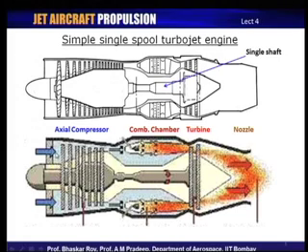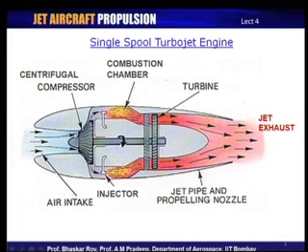They are actually individual compressor units lined up one after another, literally lined up in a sequential manner, and the compression process happens one after another in a sequential manner, so that the compression is built up over a number of compressors, literally. Now, in a centrifugal compressor, it produces compression in one go.